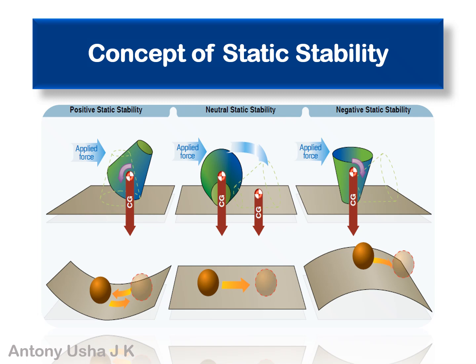In negative static stability, an aircraft is negatively statically stable if, after a disturbance, it generates forces or moments that amplify the deviation from its original position, where we can see here in the last picture the negative static stability, it deviates from its original position. In this case, the aircraft will continue to diverge from its original attitude without corrective actions.